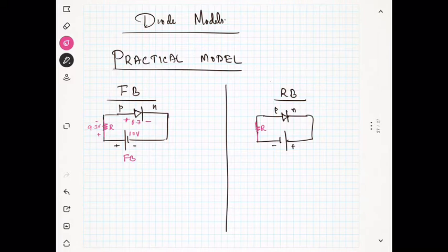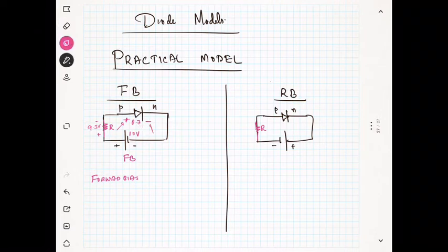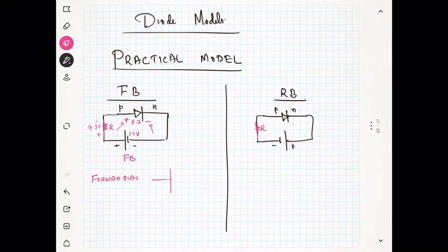If you don't put the resistance, the current through the diode will be very, very large, and finally your diode will get damaged. So we can draw the model for the diode like this. In forward bias, the diode is showing a voltage of 0.7, so plus and minus. Sorry, the minus is here. So I can draw the figure for the diode like this, plus and minus.